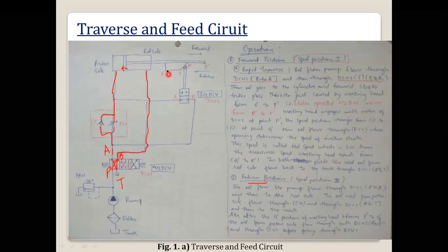From port A it will go to the tank port. So in this position, what was happening? The roller was at the R dash. Since the rod is coming backward, the roller will be moving forward. When the roller comes to the Q dash, it will engage. The roller will actuate. Because of the actuation, what will happen? It was at the closed position, so it will get open. Open means A1 to P1 will be connected. Okay?